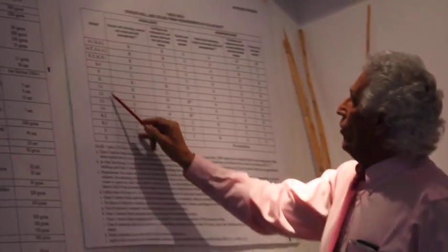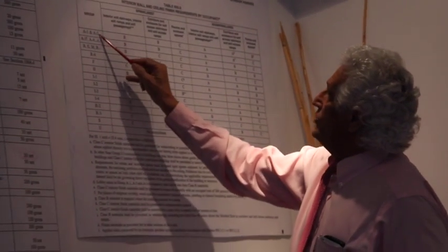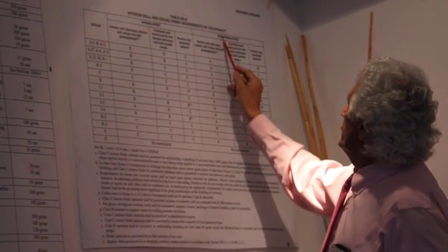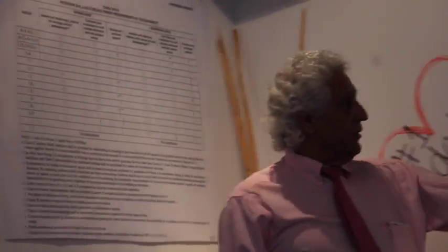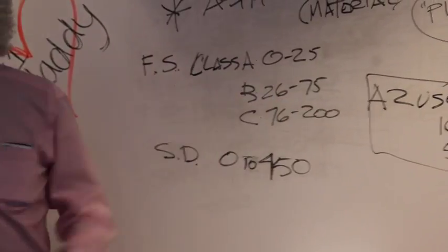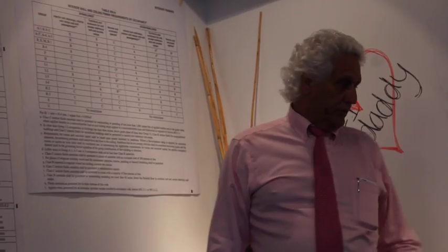If you notice in a stairwell for an A2, a restaurant, if it's not sprinkled, it has to have a class A rating. If it is sprinkled, it can be a class B rating. In other words, it has a greater flame spread rating. So again, it's the benefit of having a sprinkled or non-sprinkled building.